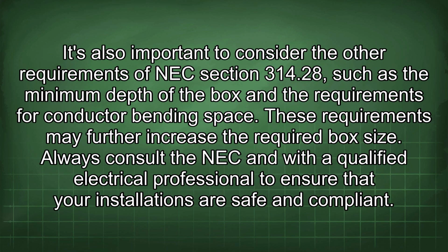It's also important to consider the other requirements of NEC section 314.28, such as the minimum depth of the box and the requirements for conductor bending space. These requirements may further increase the required box size. Always consult the NEC and a qualified electrical professional to ensure that your installations are safe and compliant.